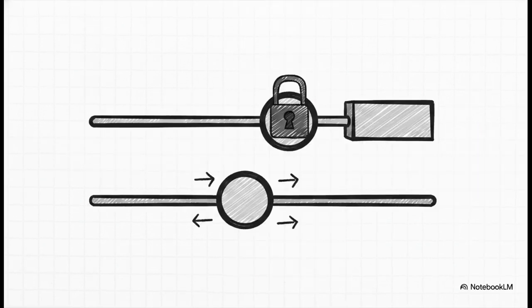And these frictions happen right down at the individual generator level, too. Imagine a generator slider hits a hard red maximum stop, or drops to a minimum operating floor. When that happens, the active set changes. That unit is now pegged. It's no longer an interior unit, which means our nice, elegant, equal incremental cost rule doesn't apply to it anymore. The leftover demand has to be shifted around to the units that are still free to move. Honestly, applying the unconstrained rule to a pegged unit is one of the most common engineering traps out there.